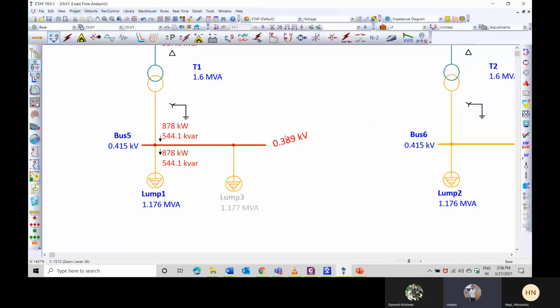Then what is the per unit of this particular point? When we convert into a percentage or per unit, how do we convert it? We have to divide this 389 by, not 1,000, here we have 415, sorry. It will be 0.389 divided by 0.415. What is the value we get? 0.937. Okay, it is the voltage which we will be getting, right?